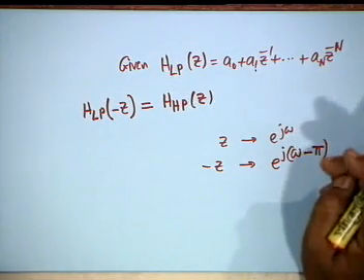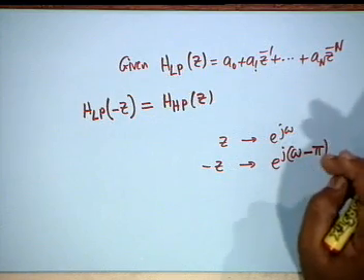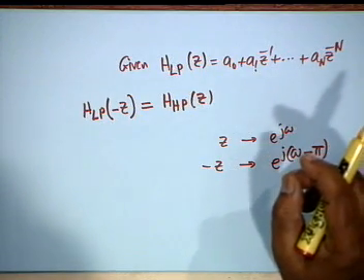So, it is also said that if the sign of alternate coefficients is changed, which means that you modify the impulse response such that alternate samples are made negative, then you get a high pass filter. So, it is a very simple low pass to high pass transformation. The characteristics are complementary. The cutoff frequency remains the same. Is that correct?